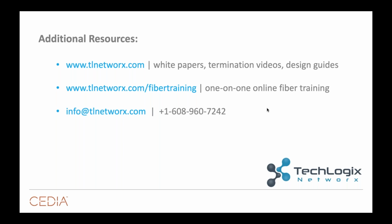What I think you will continue to be seeing is hybrid installations, where you're still pulling that twisted pair cable for a lot of your short distance patching, but certainly your trunk lines, certainly your 8K and ultra high resolution video distribution, that's where you're going to be using fiber optic natively. Don't give up Cat 5s yet. Still pull your Cat 6 cables. What I tell everybody when they're pre-wiring is, instead of pulling 2 or 3, pull 1 twisted pair, 1 fiber. You're really not going to regret that.